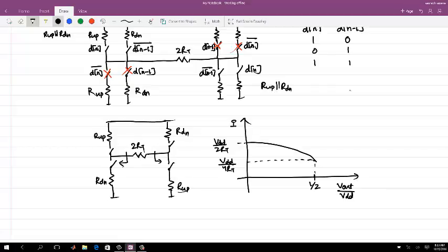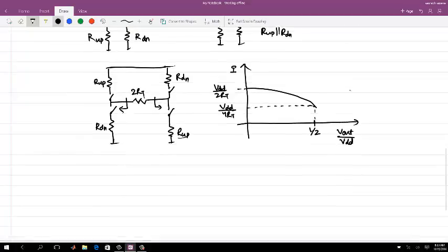This supply is coming from some regulator or somewhere. And if you are switching the current between two values, either the regulator has to respond to that switching current, or the large switching currents can also cause more disturbance on the supply and to the other blocks. So the two problems which you see here are in this way of implementation.